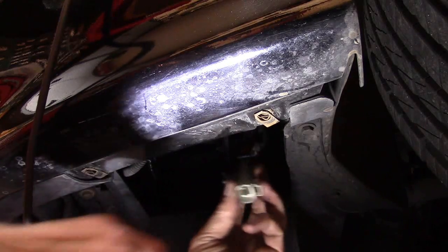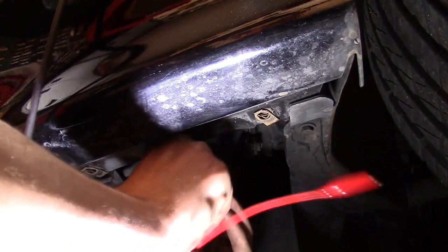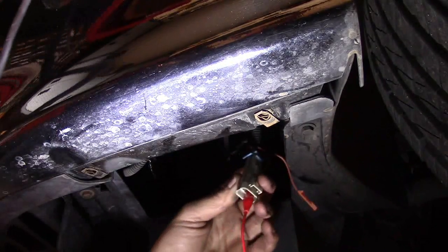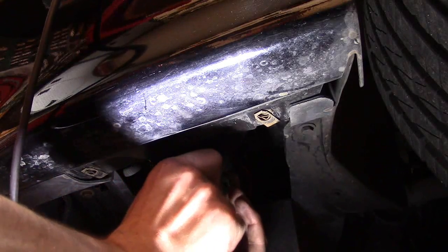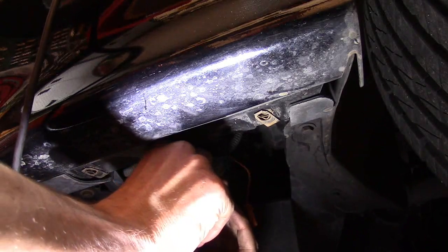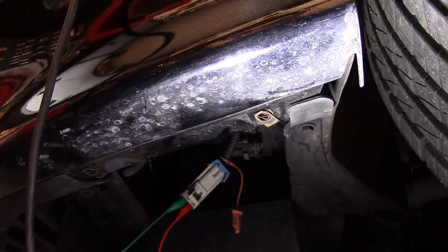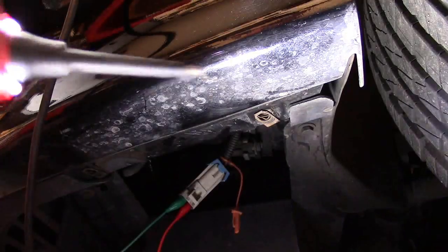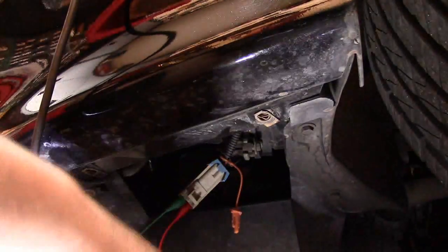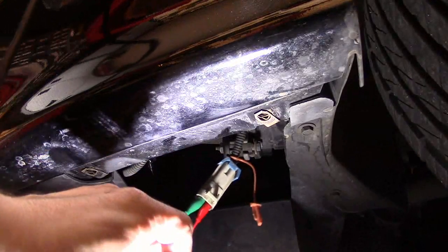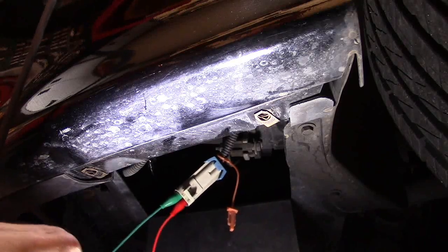But what I'm going to do is I'm going to feed a little extension wire here to the connector for the power. And I also have one here for the ground. And all we're going to do is just apply battery voltage directly to this motor. And this should be very standard for you guys. And what I'm going to use is, once again, you've seen this before, my power probe, but you can easily just do this with jumper cables. All this is just connecting the ground and power directly to the battery.